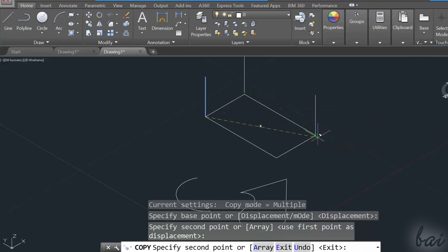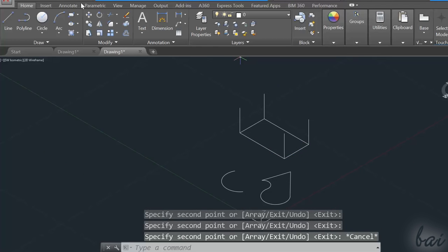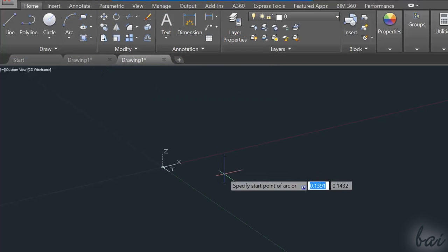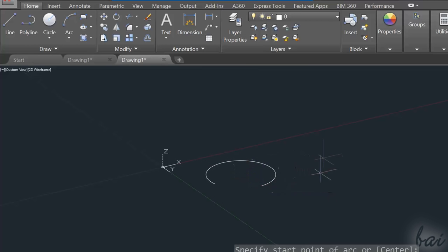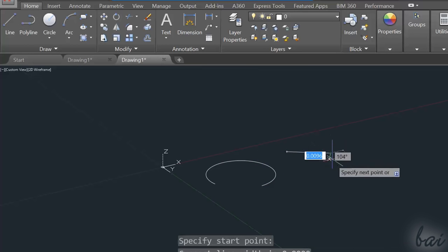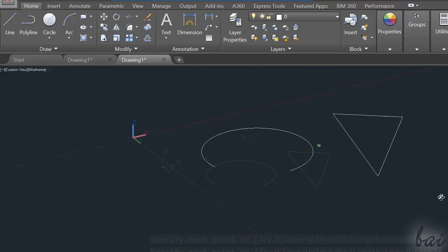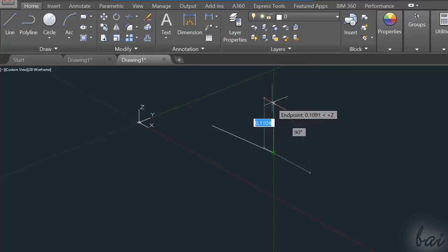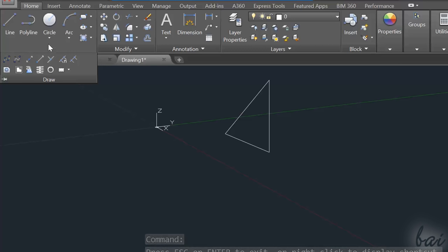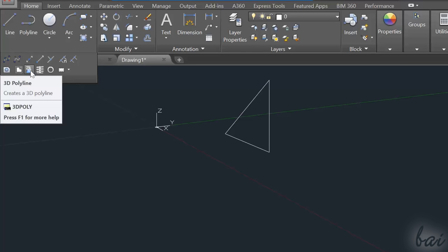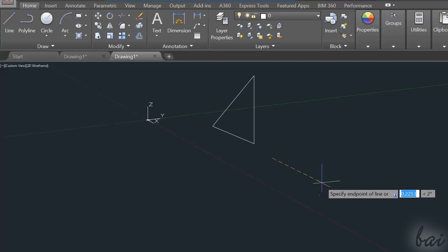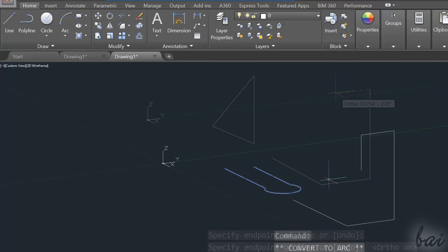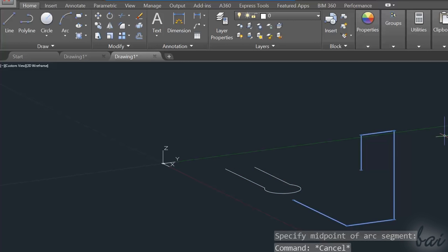You can use 2D drawing tools to draw 3D objects as seen, but this is not recommended since these are quite hard to manage. In fact, circles, arcs, and polylines always spread through either the x or the y directions only, so you are never able to draw these objects along the z direction. Just the lines are able to do so, and another 2D object called 3D Polyline tool inside Draw. These 3D polylines are just like the 2D polylines, with the difference that you can spread these along the z-axis, but you can't make any arc or curved side.